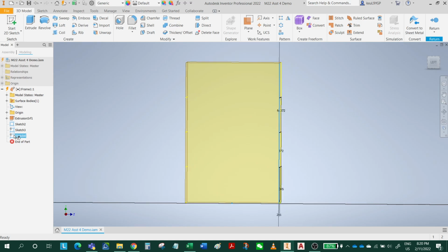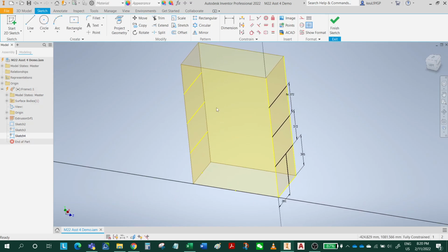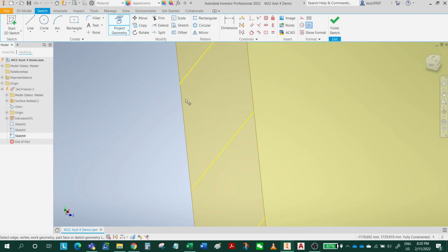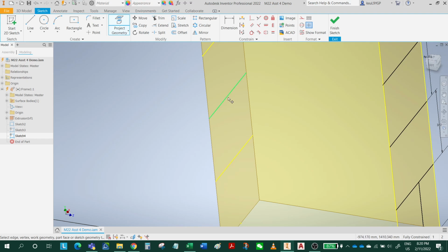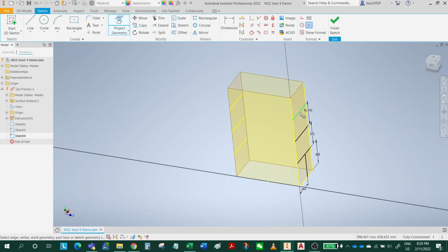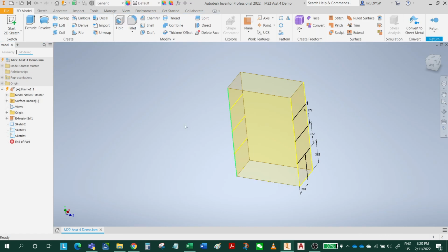I did this sketch, all right. I'm gonna project geometry with those lines. I'm gonna project geometry from here. So see, create a point. Project geometry. See, there is a point here. Look at here. What is the change? So click here, you're gonna have a point, right? Same thing. You're gonna project geometry here, here, here. All those 6 lines project geometry on this front surface, front plane. You have 6 points.